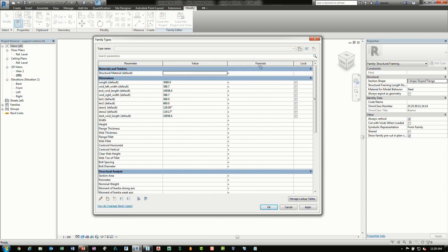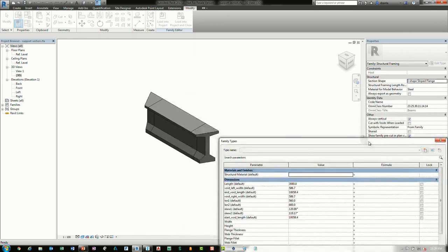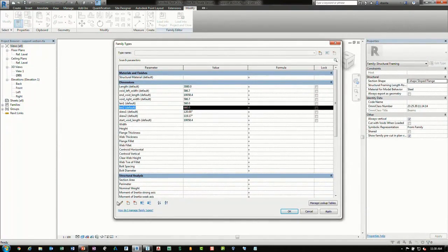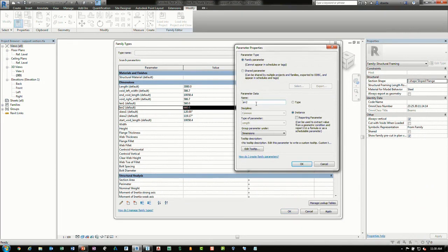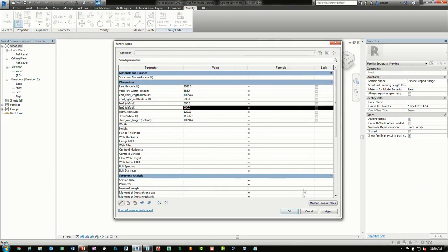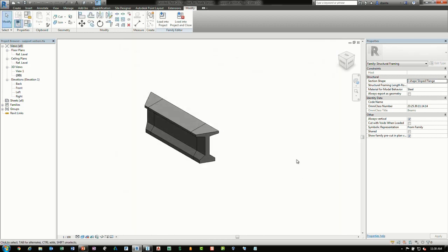So there's a lot of data that automatically gets built and put into the family. So the question really, again, becomes, do we use that data? Do we not use that data? How do we massage that data? Can I select any one of these and go into the property aspects and make changes? Yes. Okay. What you're going to notice using this workflow and looking at the InfraWorks bridge that goes out of InfraWorks into Revit is that some of the families are very intelligent, like you're seeing here. Some are not so intelligent. Okay.